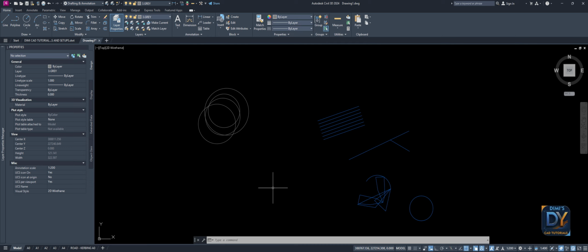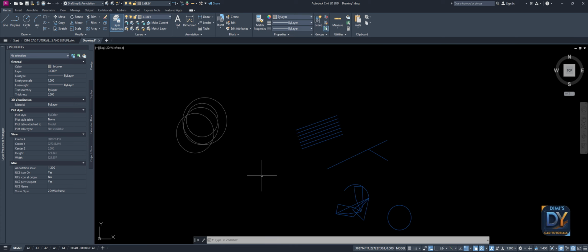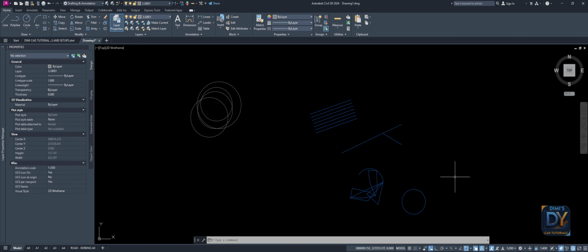Let's say you've got 1,000 objects, 1,000 elements, and let's say 20 layers, and it's going to be so overwhelming. Let's say you've got the services crossing and roads and all kinds of stuff, and you don't want to have all that. All you want is your plot layers, like external walls, internal walls, your deck. Only the information which you need will be visible. This is how layers work.